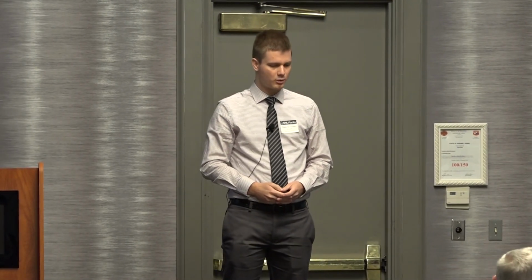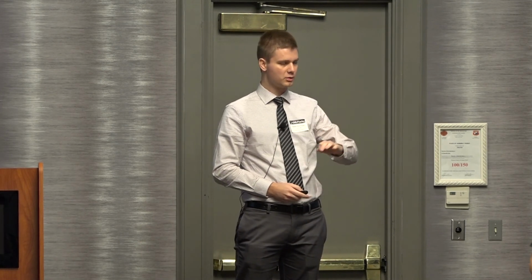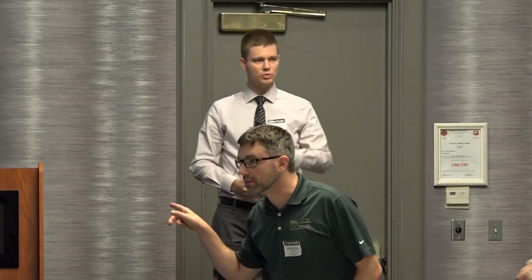Hi, yeah, this might be a dumb question, but why in the transition region did you need to worry about combining and the phase? Why not just take one or the other? That is a good question. The reason for this is because we want a nice, smooth transition region across the two. We don't want any discontinuities across that region. If you just use one, you're still going to have to cut off and switch to the other receiver at some point.